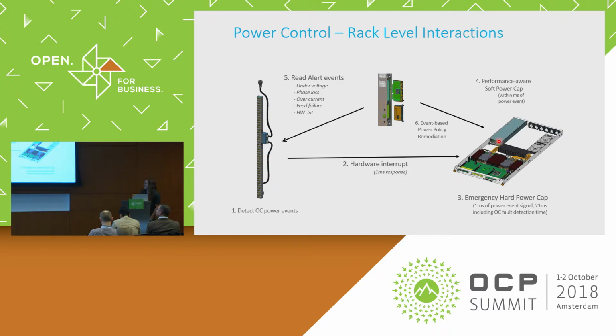So it all leads us to moving away from having static power policies on servers and having servers run at a set power limit. If you're running servers at a set power limit, they're not running to their full performance. You want to have them ungoverned or unrestricted. Let them run as high as they like, as long as at the rack or at the row level, cumulatively they don't exceed those hard power limits of the infrastructure.